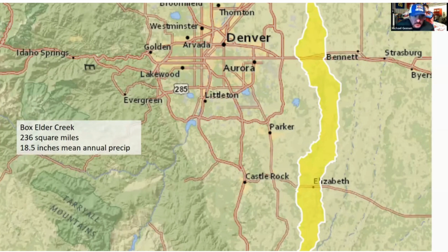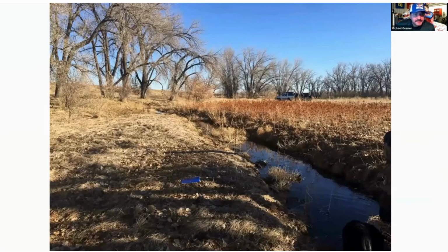So, looking at some of the watershed coefficient factors and some of the things that we've looked at in the past that Dave's has talked about, this would give us some kind of indication of where we might expect our cross-sectional area to fall in. So a couple pictures of the sites here. Here is a cross-section coming right through the site. So, one of our first observations was that for a 236 square mile drainage area, you would expect it to be a pretty large river, right? We weren't really seeing that in the field.